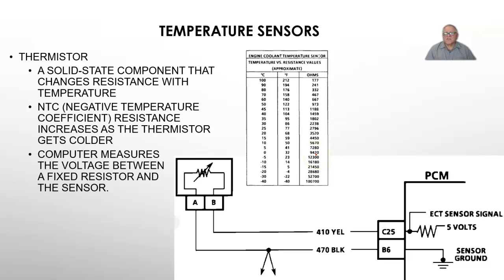When dealing with engine performance or drivability, it is much more important that the computer see changes in the colder range in order to keep the timing accurate, the amount of fuel going in to keep the engine running correctly, and the emissions low. Once you get up above about 160, 170 degrees, the computer makes no more adjustments from temperature.